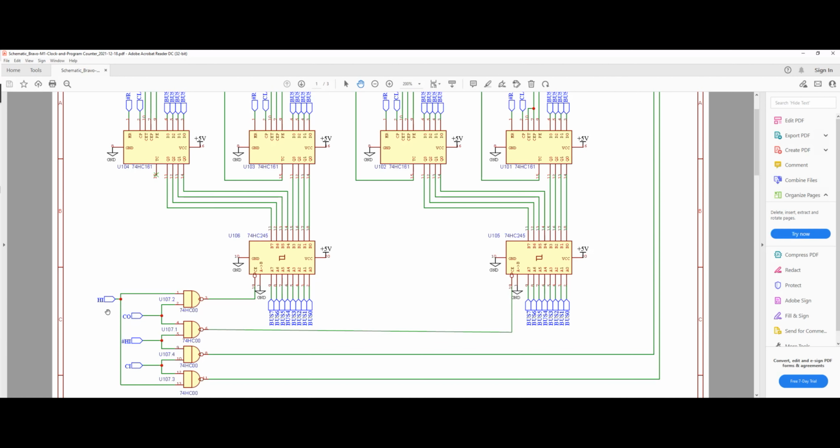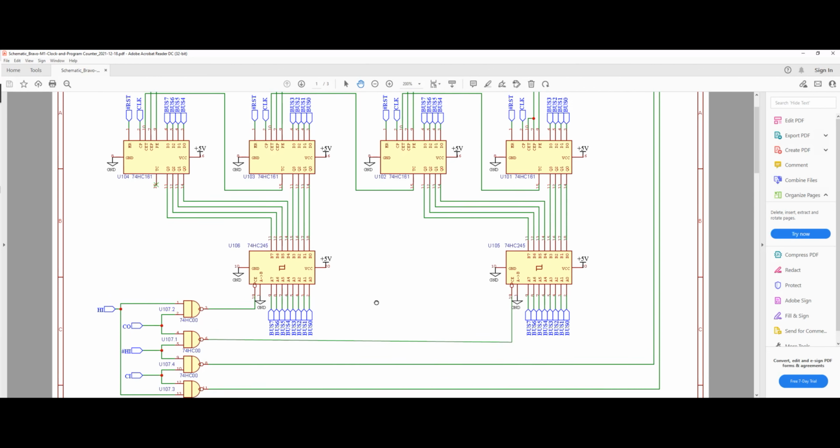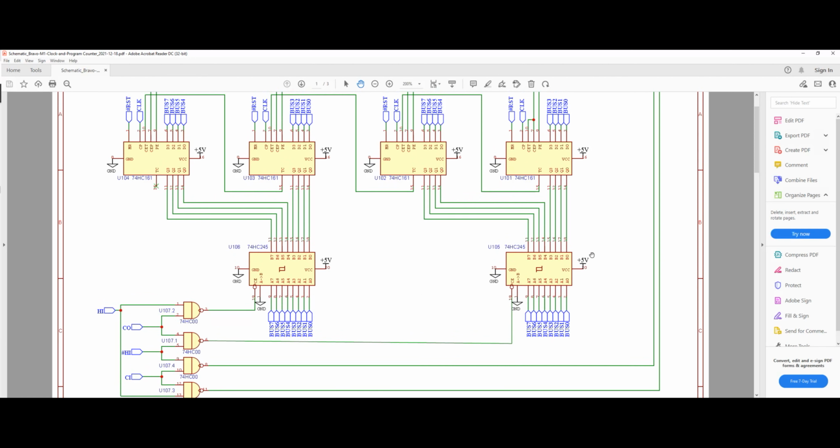This signal is generated in our control logic, and we're going to look at it when we are actually building the control logic. However, when we are generating that HI signal, we are also inverting it using a 74HC04 chip, which basically gives us the original signal and the inverted version of it. Now let's focus on the output side first.